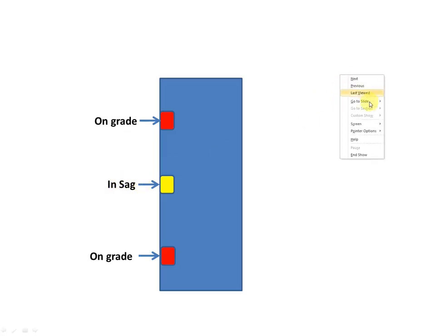I will tell you about the flow direction tracing here. I'll use this pen tool. Runoff from this part of the road and the surrounding area, meaning these commercial buildings, initially comes into this inlet.